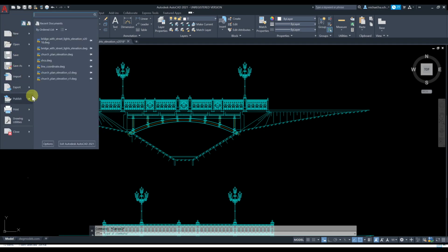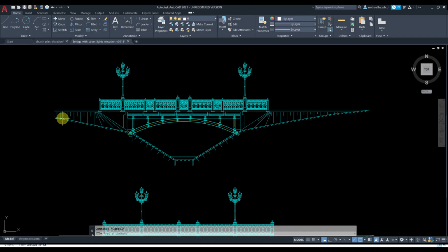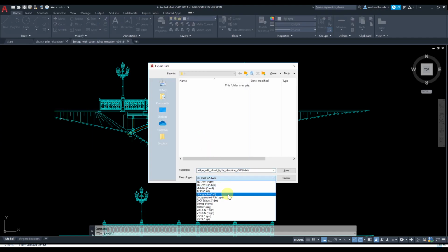You can also export things. So big A, go ahead and export to a variety of formats. You can export it to BMP, an image file format. You can export it to STL. This is 2D, and you're going to be cutting some holes, wire cut. You can save it in an STL file. STL files are also used for 3D printing. You can export it to IGS and open it with other CAD software.